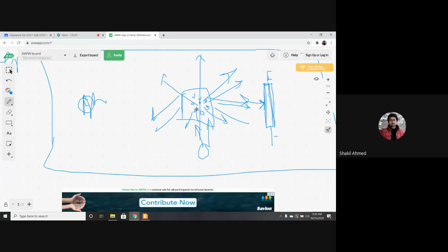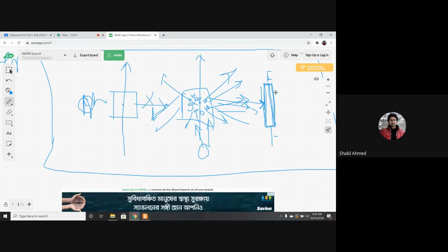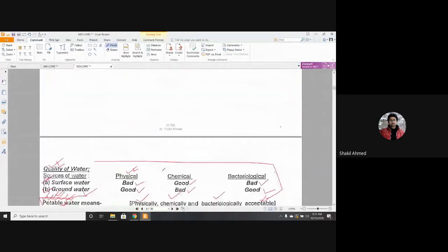The higher the turbidity, the higher the silt, clay, and other turbid materials in the sample. Higher turbidity means higher reflection of the light and a higher signal from the sensor. If you do not have any turbidity, the light will directly pass through, there will be nothing to detect, and so no signal. From there you can calculate the turbidity. Okay?